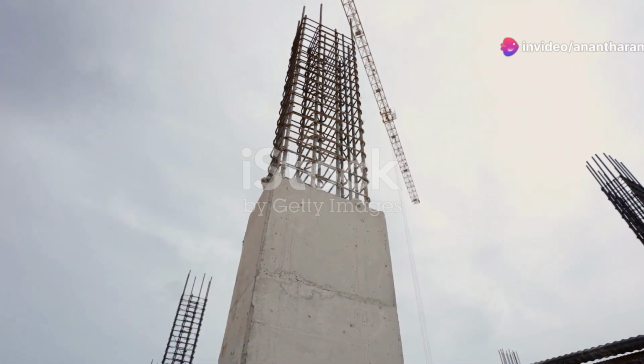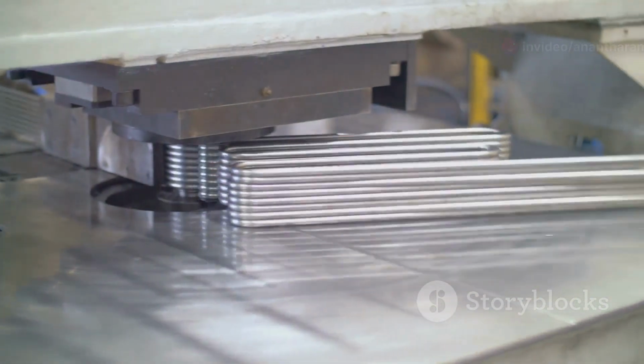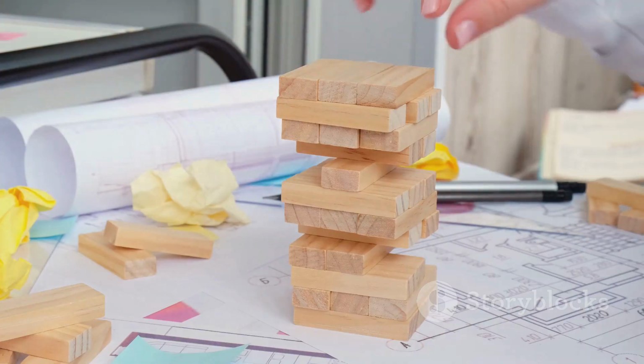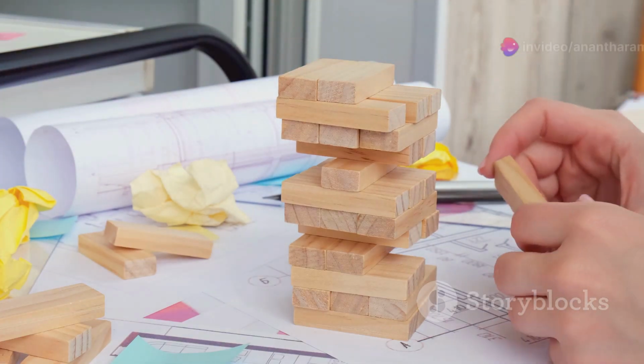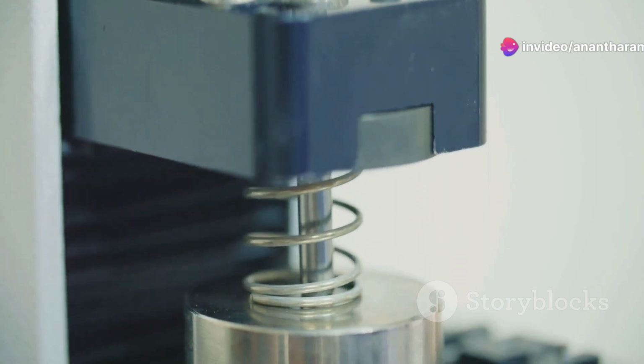Imagine a tall, slender column supporting a heavy load. As the load increases, the column may suddenly bend sideways. This phenomenon is called buckling. Buckling is a stability failure, not a material strength failure. Buckling occurs when a column becomes unstable under compressive stress.